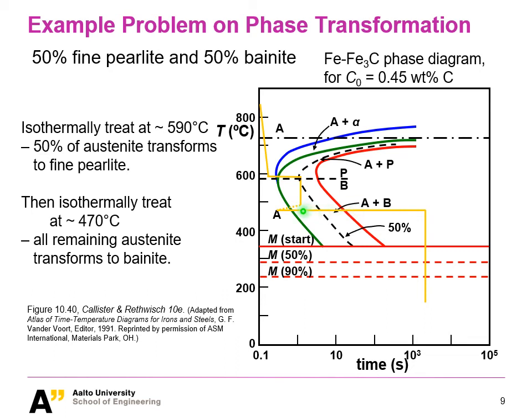because if we're going to continue with the time, but your phase composition is not exactly here, because if you just put it here or continue here, it is somehow giving you an impression our microstructure is something about, let's say, 30% of bainite and 70% of austenite, right? So this is the 0 of bainite, and this is 50% of bainite. No, actually we are having 50% of fine perlite and 50% of austenite. That's why we go back to the austenite region.